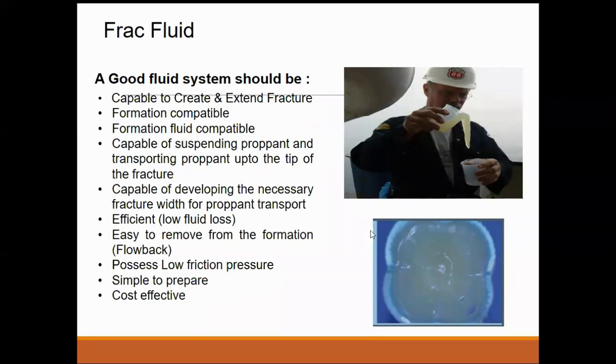So the fluid should have such viscosity that it does not let the sand settle in the pipelines or in the formation. You should always be able to keep your proppant in suspension or in slurry mode. It should not solidify, so that it can flow. Right. So, capable of developing the necessary fracture width.